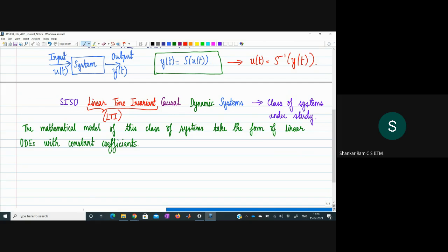Even if you recall the mathematical model that we derived as the linear bicycle model, between the steering input and, let's say, the yaw rate or the yaw angle, you could observe that although linear, it was quite an involved model. Now imagine inverting that model, where you want to write the steering angle as a function of these things.